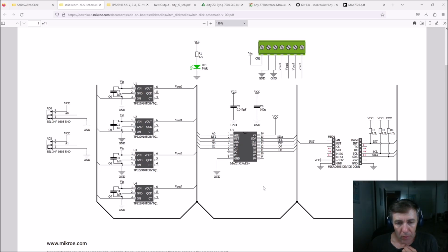It turned out that there is a problem with the reset pin. If we look at the module schematics, it doesn't go anywhere apart from the reset pin, which means there is no pull up or pull down resistor.